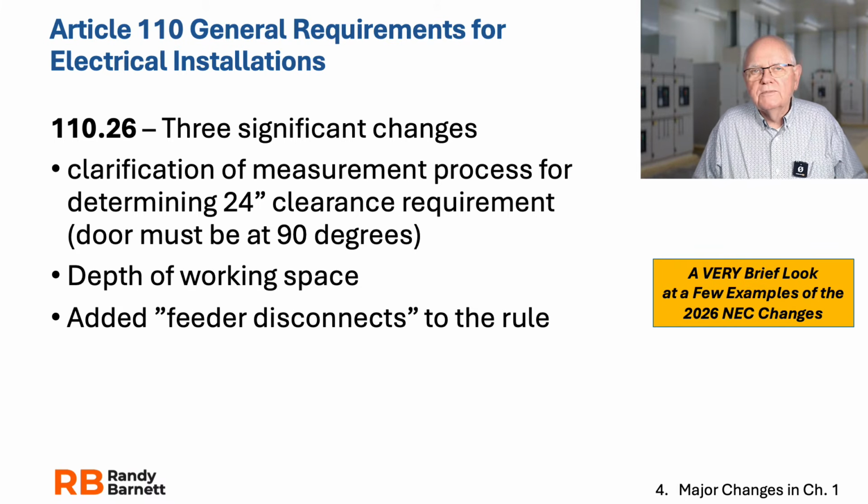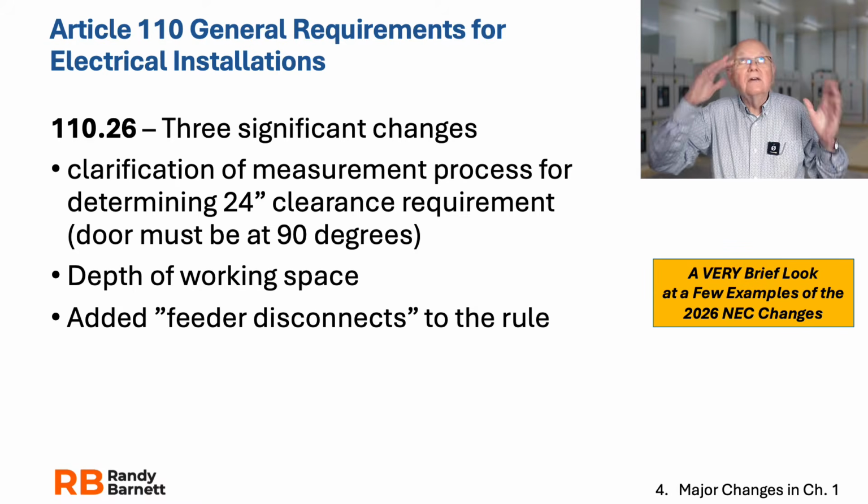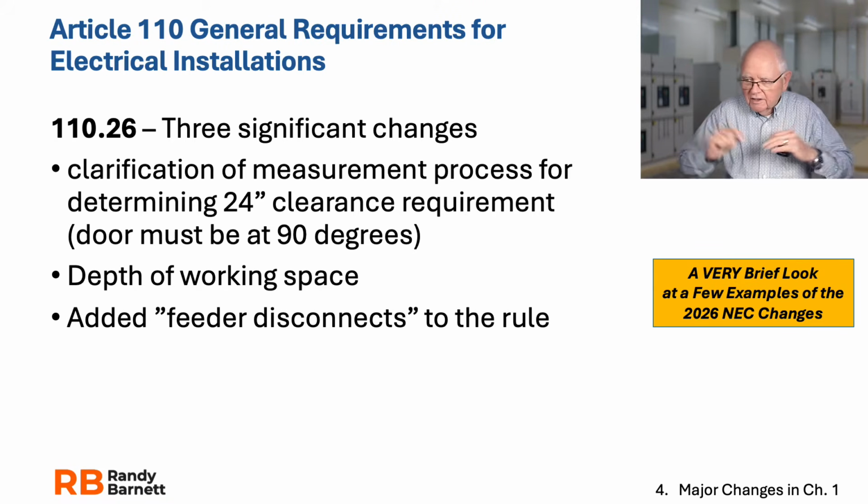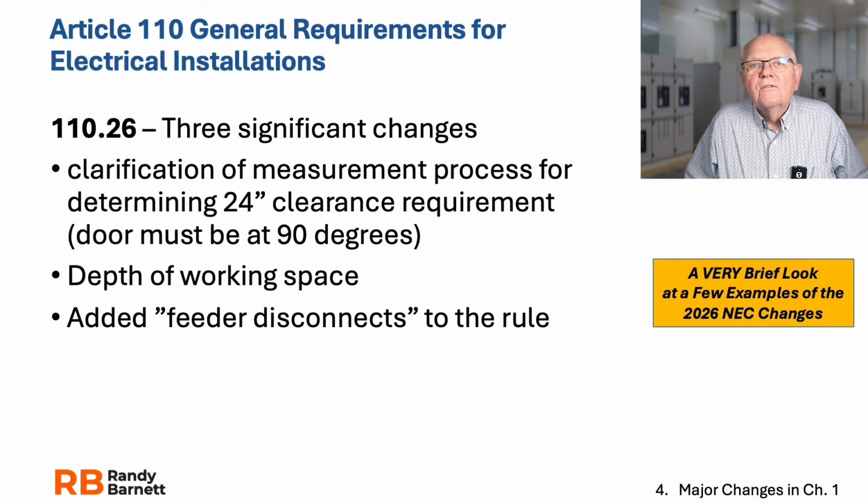110.26, of course, has always been an important one in the code. And that is for our working spaces about our electrical equipment, height of working space and distances, and so forth. So anyway, there have been some significant changes there. One, clarification of the measurement process for determining the 24-inch clearance requirement. And this is on your door opening.